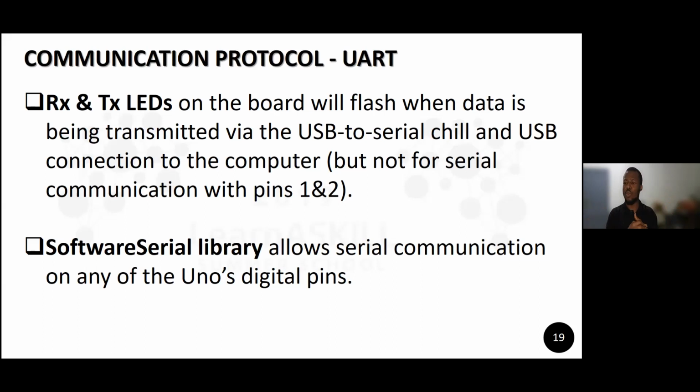That is what the Atmega16U2 does. It serves as the bridge controller for USB to serial communication. Some Arduino clones use ICs like the CH340 or FTDI programmers, but genuine Arduinos use the Atmega16U2, as I talked about yesterday.